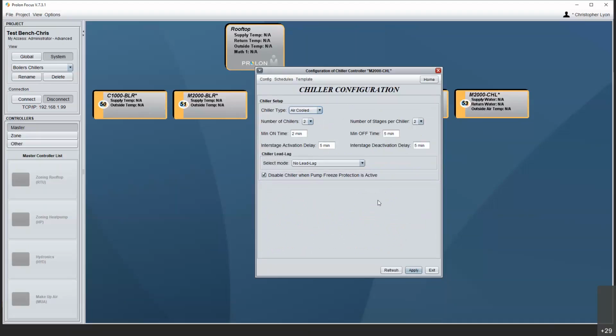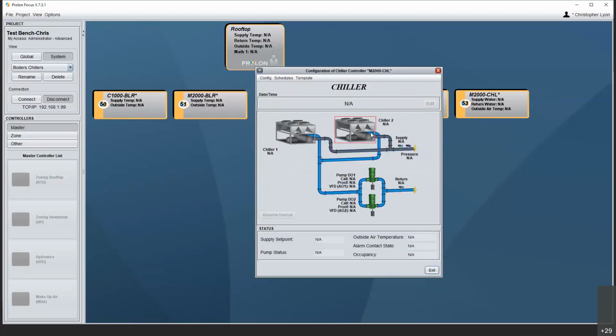Notice that all of my water temperature restrictions are gone. I don't have any air temperature or head pressure type restrictions in there, because I'm going to rely on the air-cooled chiller to handle that on its own. It should already be equipped with its own limits and safeties. We're just going to be providing an enable signal to that chiller or chiller stage to push it to run, to allow it to run.